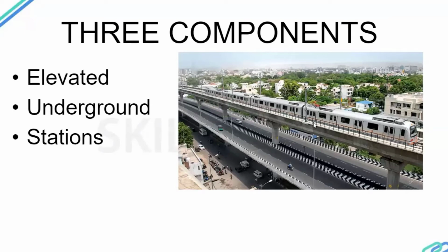Also, since the metro is running on that, we need to take into account the rail structure interaction, that is the dynamic effects of rail moving onto the structure, as well as the dynamic effects of the vehicles which are plying on the highway part, level 1 of the bridge. That needs to be taken into account.